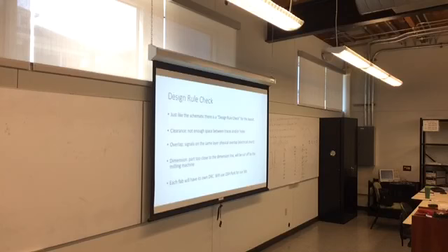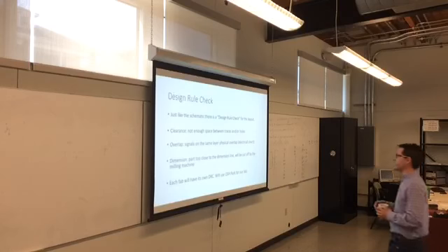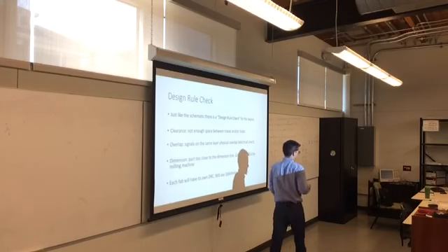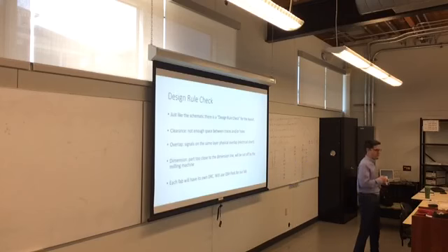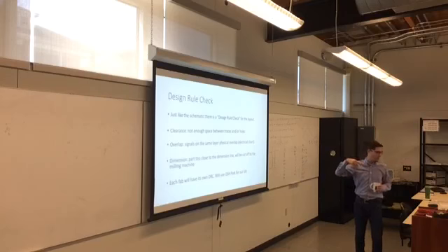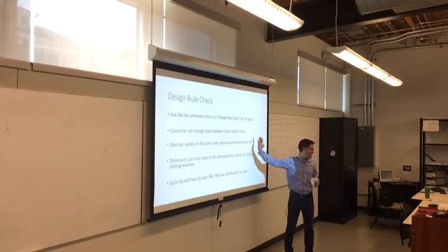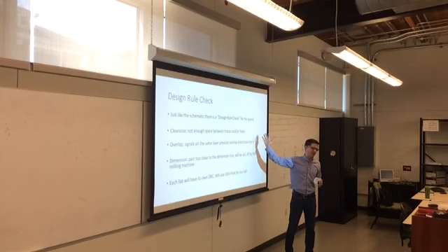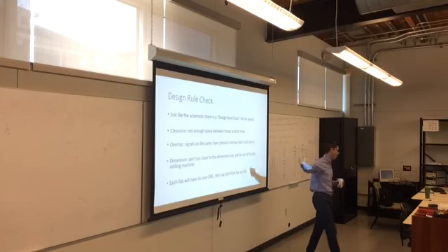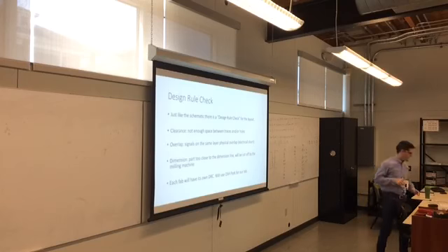There's nothing in the tool that prevents you from putting components outside the space of your board. So there's going to be a dimension line, and that is where the mill at the fab is going to cut your board. And if your wires are too close to the dimension line, your wires are going to get cut. And they're just going to be disconnected. So any design for any fabrication house is going to give you rules on drill size, on clearance, on different things that matter.